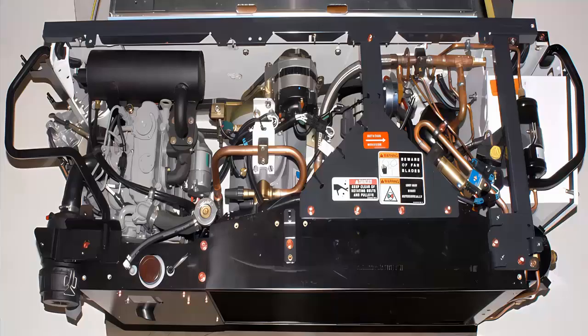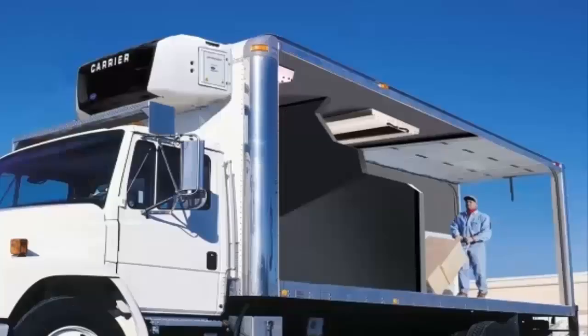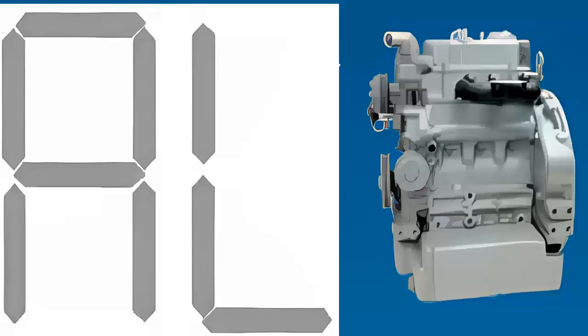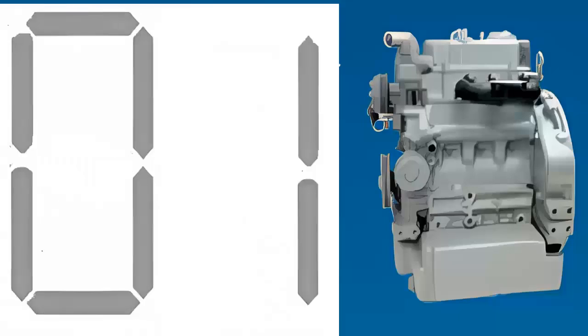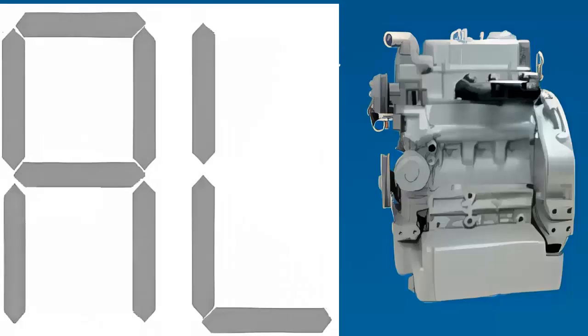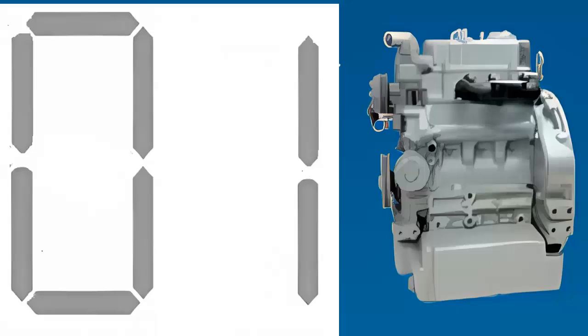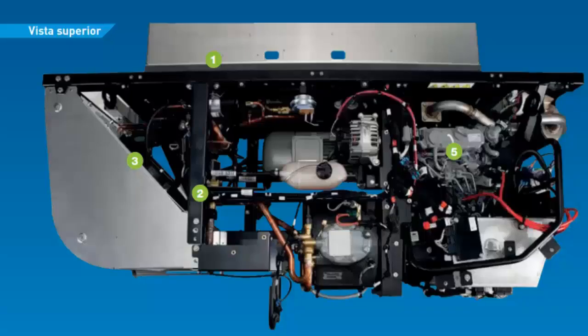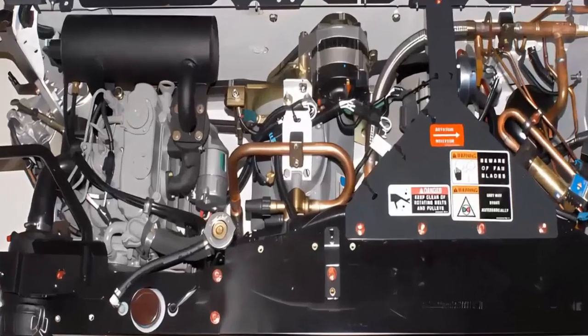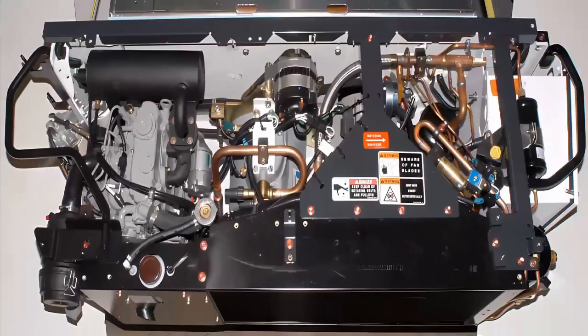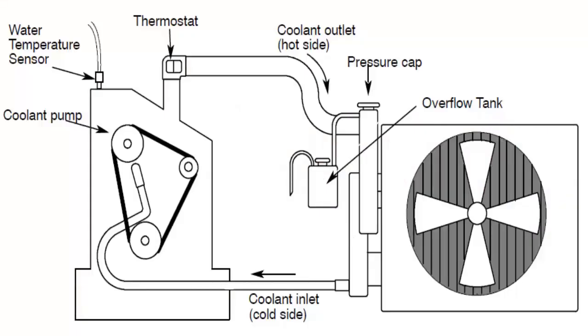2. High engine temperature driving the refrigeration system compressor. This fault is identified with code AL1 and occurs when the engine powering the compressor exceeds its safe temperature, possibly due to a low coolant level. The main causes include thermostat failures, fan issues, or blockages in the radiator.